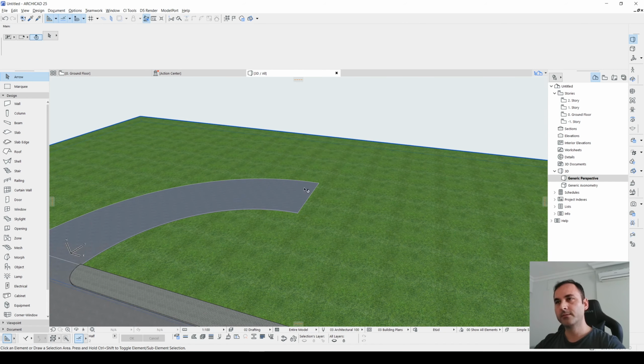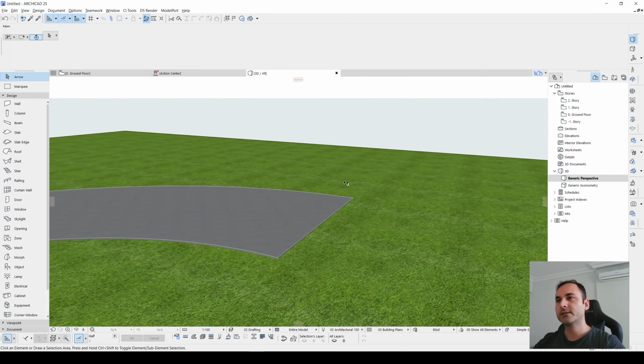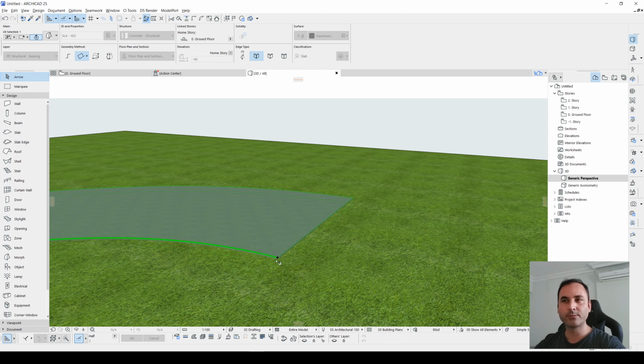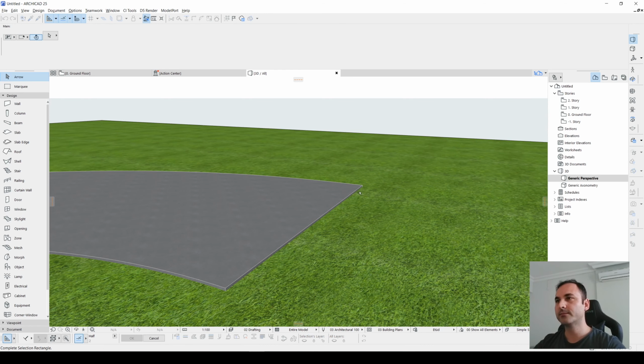After that, we will select this face, but if we click our morph, we cannot directly click that face. Now, on the top of the window, we have an arrow here. Let's click it, and we have another option, which is unfilled type. It says sub-element. Now we can directly click our face, lines and points. Actually, we cannot click our points because ArchiCAD doesn't work that style. Anyway, let's click our face.